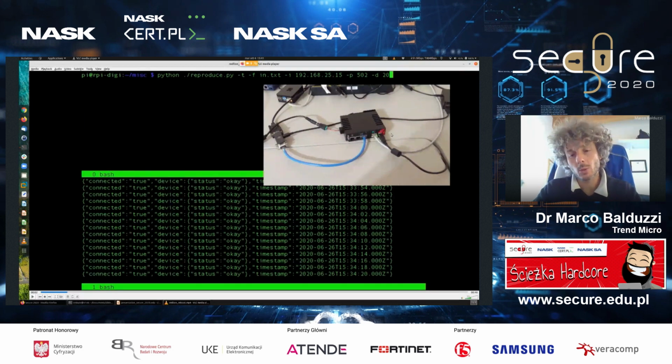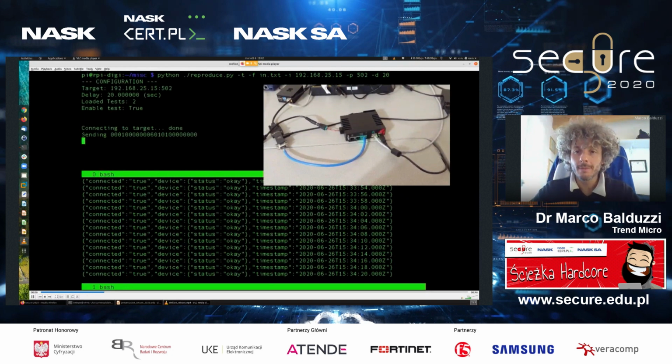Now I'm going to send the packet. My packet basically consists of a read request for an address which is 0. In this specific case, this data station has a problem with indexing these values. So 0 falls outside the memory range of the device, to make it simple. And you will see that basically the device reboots. You can see that there were some red LEDs. You can see now that there is a blue LED, which is basically the rebooting process.